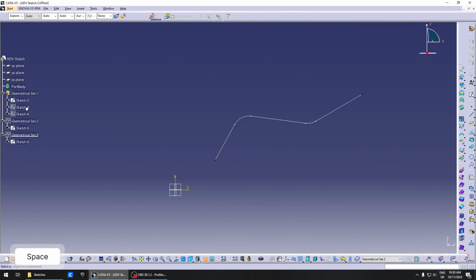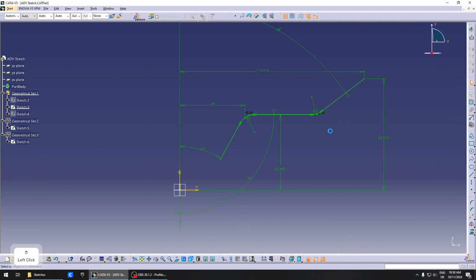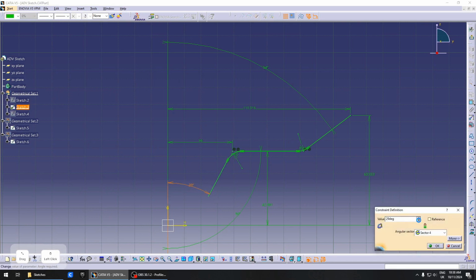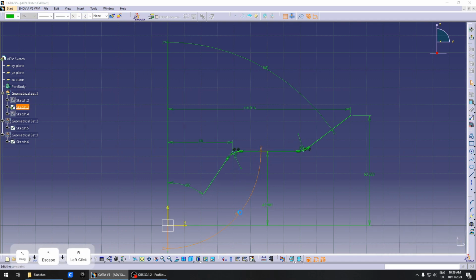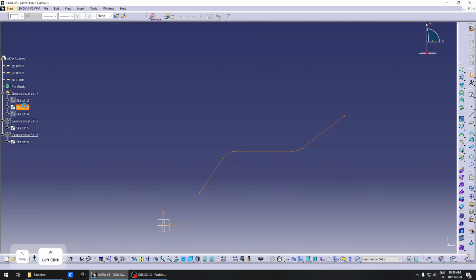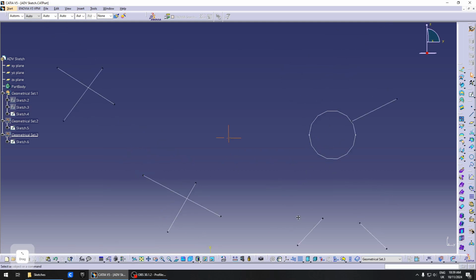What you actually want to do is to have it more like this. As much as you can, constrain to the axis system. So then when you actually modify something, you only modify that element. See? Sometimes it may be unavoidable, but see how this changes only the stuff you wanted to, and not your entire sketch. This is a much better practice than doing it the other way.